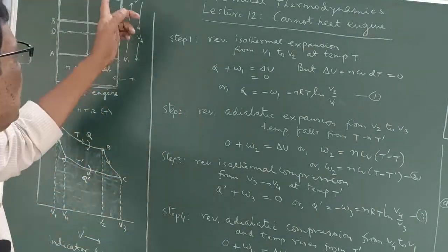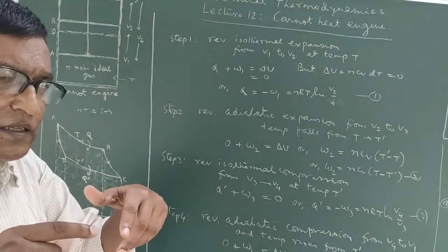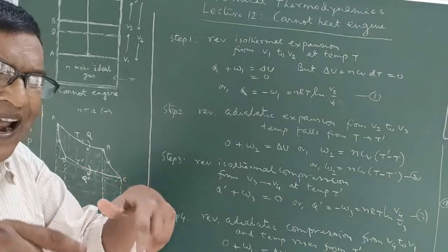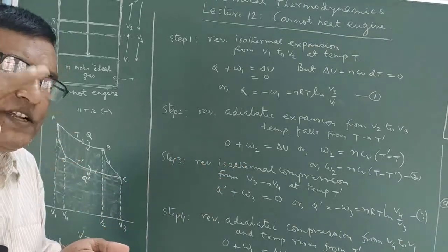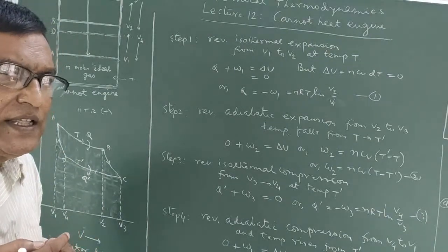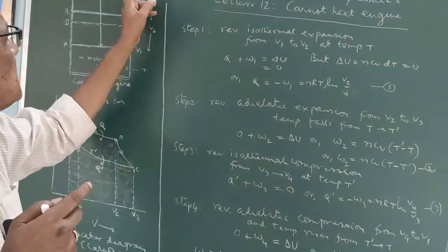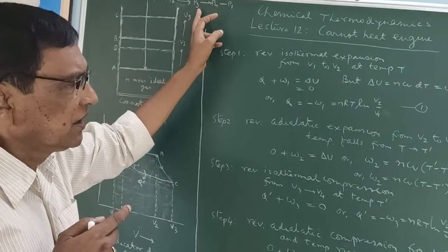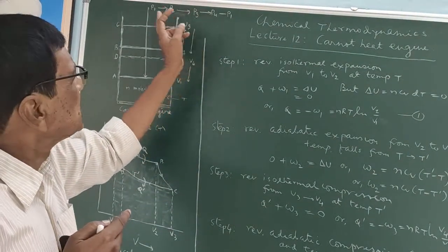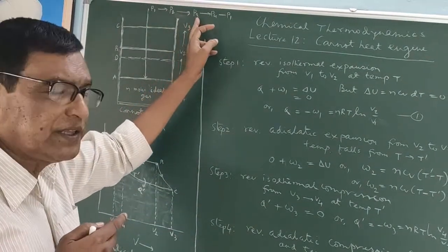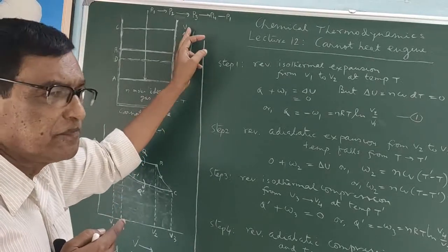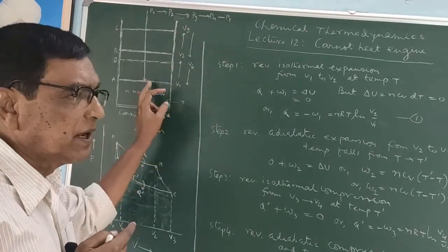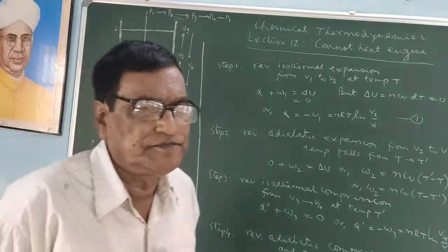And now again, picking up one grain at a time, the load is decreasing, and so pressure falls from P2 to P3, and volume rises from V2 to V3, as no heat is supplied to this engine.